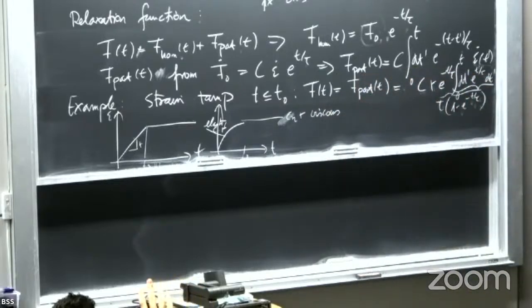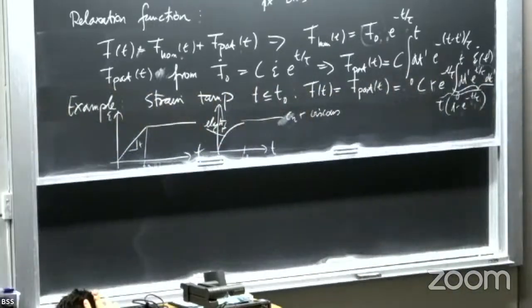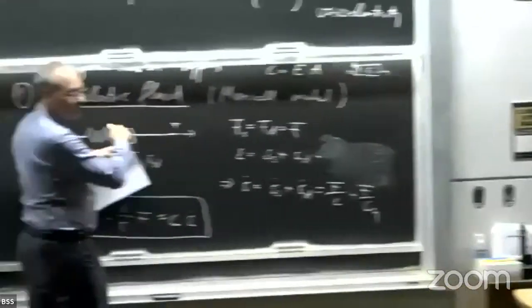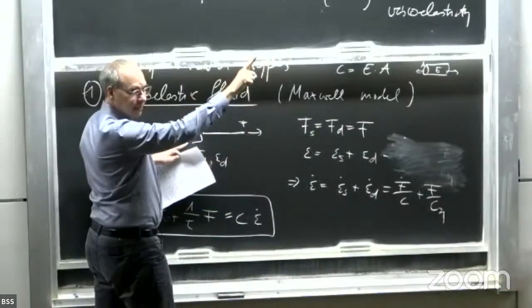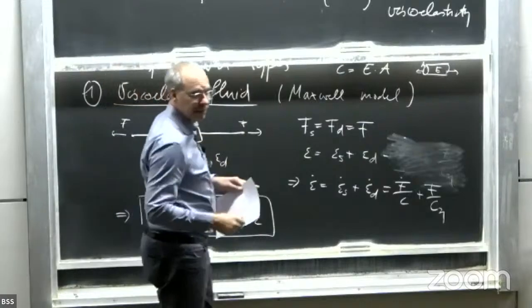Okay, so what happens here is that as you pull the Maxwell chain, in the beginning, you actually stretch this spring here. This is the elastic response. Then the spring is extended to some extent. It doesn't extend anymore, but you pull out lengths from here. And then you would go infinitely with pulling out lengths from here, with a constant strain rate.